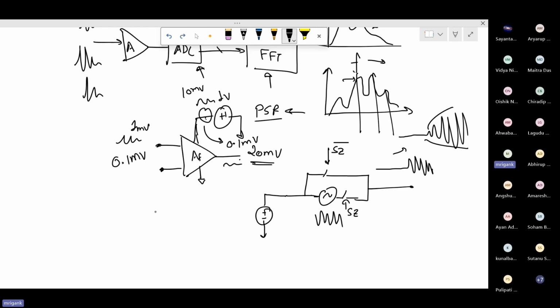So basically, what we need is a changing gain. The changing gain can easily be obtained by changing the bias current of a differential amplifier or something like that. If you change the bias current of that, that can also help. So that will reduce the gain to a certain extent initially. Many things can be done.